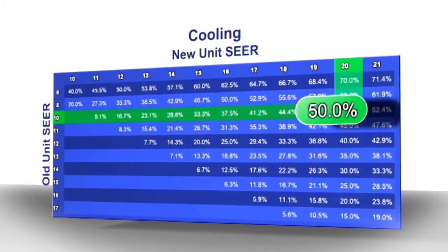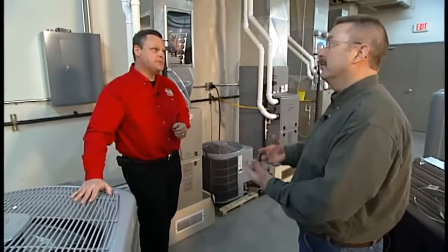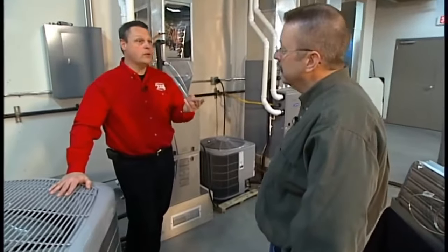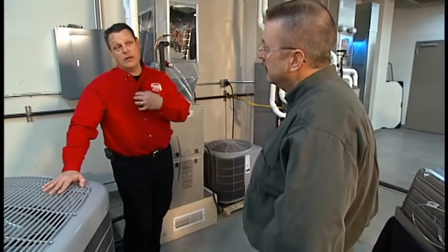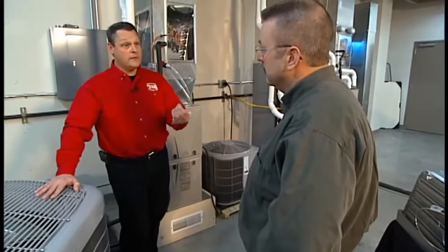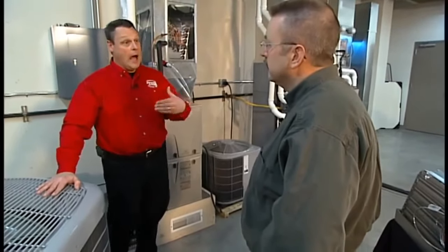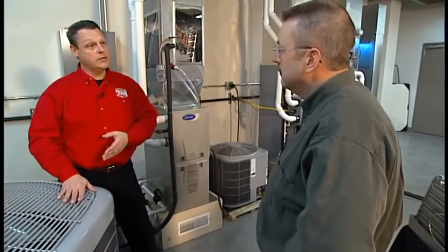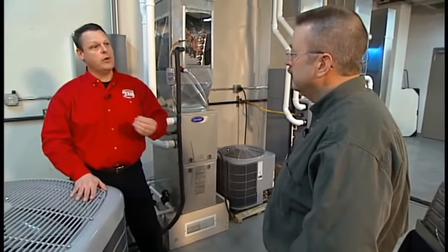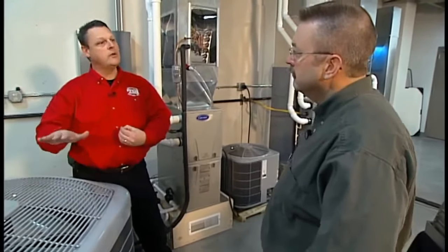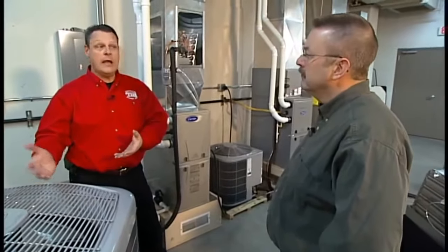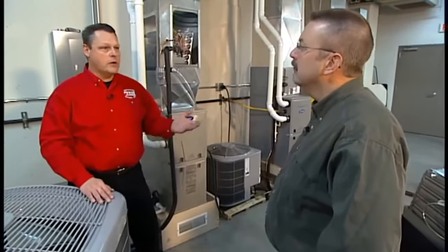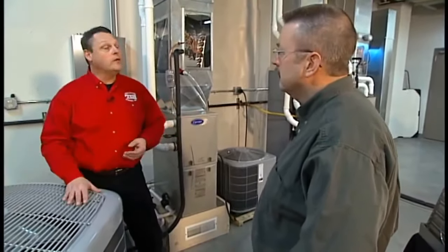Okay, but let's face it, in the upper Midwest, we don't run it continuously a lot of the time. Exactly. So in our market, there's a couple things that we really look at. If I, as a consumer, have indoor air quality issues where I'm really affected by pollen and dust and things like that, I may never open my windows. I may go right from running the heating in the wintertime and transition to air conditioning in the summer. It would then be much more important for me financially to upgrade to a higher SEER unit. It's going to save me money, and I'm running it for a much longer season than another individual who may only turn it on in the hot months of July and August. They don't need it as efficient at that point.